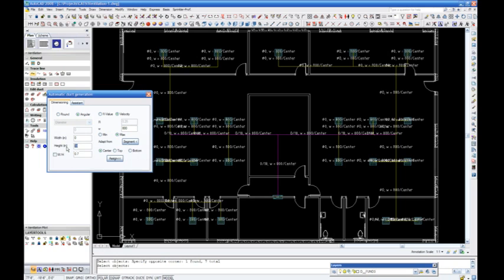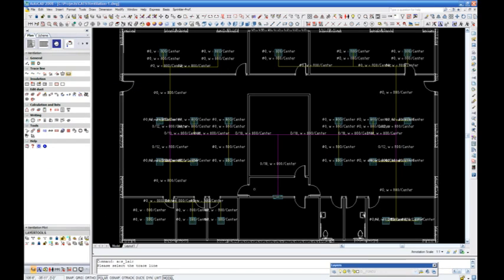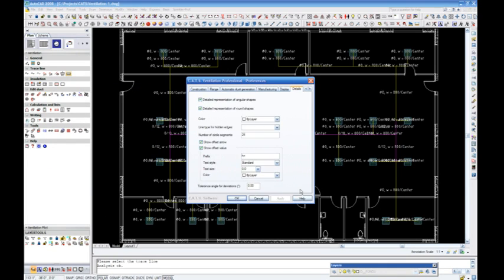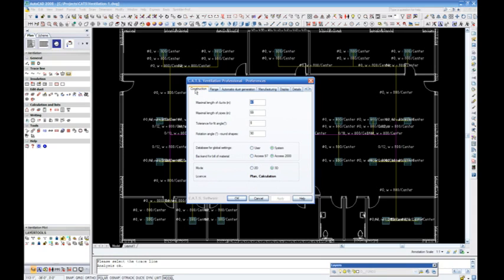We will use the defaulted 18-inch dimension. In width, we will select 0. The software will calculate the duct width according to the velocity. As the air quantity reduces, we now change our duct height to 12 inches. We are now assigning our duct system to a 3-dimensional drawing by selecting a start point at the fire damper.